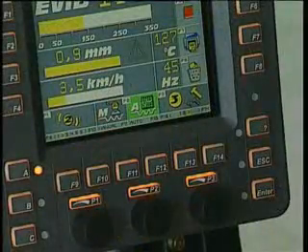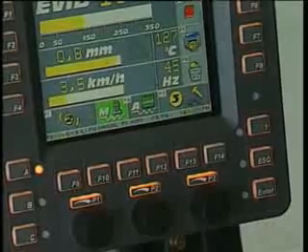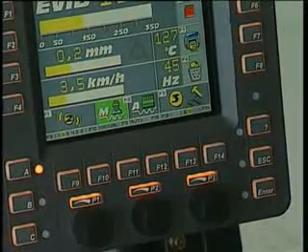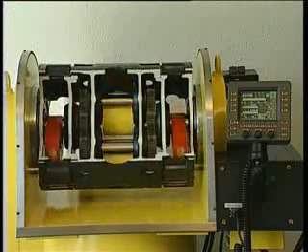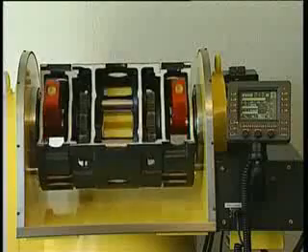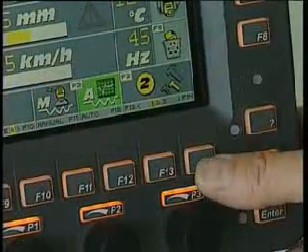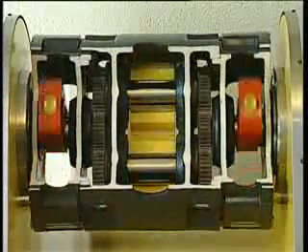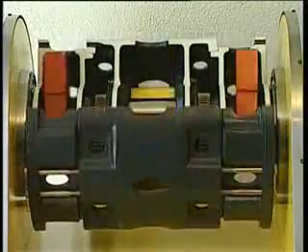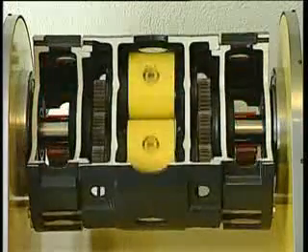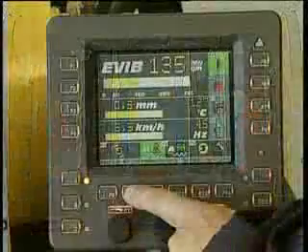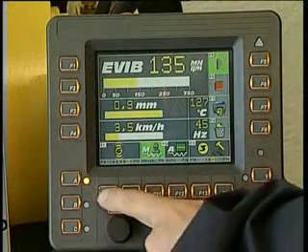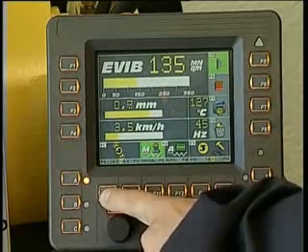Asphalt Manager can be operated automatically or manually. In automatic mode, compaction is controlled and optimized by an intelligent system. In this instance, 3 different control ranges can be set. This means that the compaction force is always being optimized to achieve the target preset by the roller driver in the shortest time possible. Over-compaction, caused by a bouncing drum, is eliminated. In manual mode, there's the option to set 6 different fixed amplitudes.